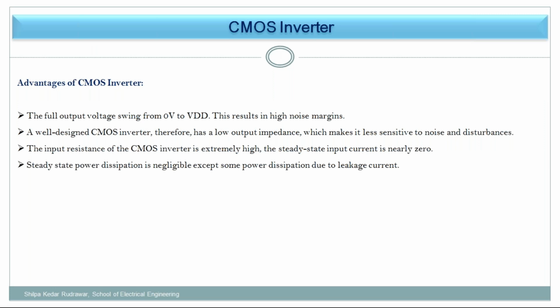Now, in the starting lecture, where we took the basics of MOSFET, I told you one important thing, that there are two types of MOSFET, enhancement type and depletion type, but we are moving towards the enhancement type of MOSFET, because the enhancement type is like a normal switch. Whenever you press the button, the device will turn on, and whenever the button is not pressed, the device is off. It is the normal day-to-day way of interpreting your switch. Same way the enhancement MOSFET works: whenever you apply voltage, the device turns on, and whenever voltage is not applied, the device is in off state.